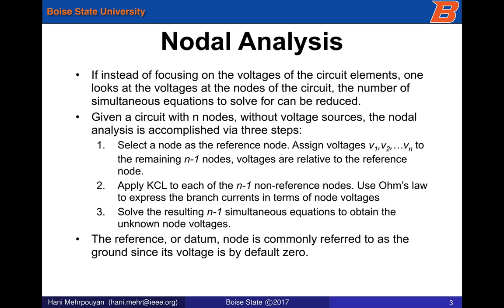Now, you may ask, what is the ground node? And that's a very good question, because that is also determined, and we will get there in the next visual example that I will give. But basically, we will select the node that is shared amongst the most number of elements to be the ground node. And if there is a voltage source there, it can be helpful in trying to determine where would be the ground node. So we would select, nevertheless, one node to be the reference node,